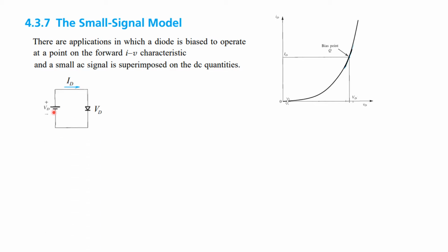Now this is the battery and we have a diode connected, although we do not connect a diode directly, but just for explanation this circuit is given. So the current flowing through this and this voltage across the diode, we plot it here. So this is the voltage across the diode and this is the current flowing. So that is how we determine the operating point of the diode.